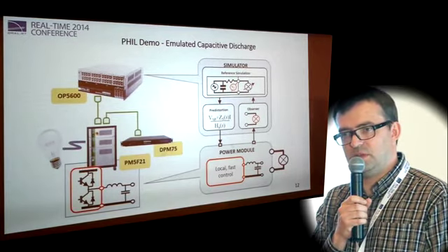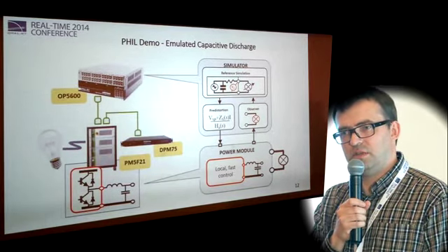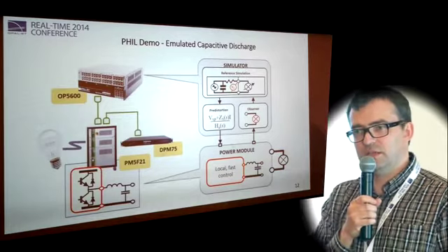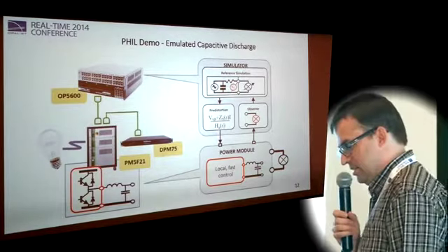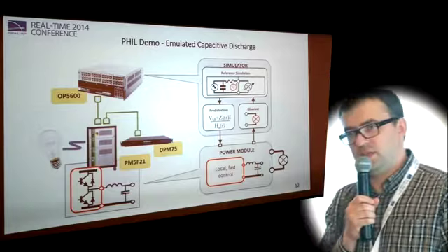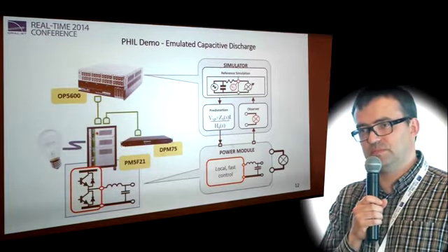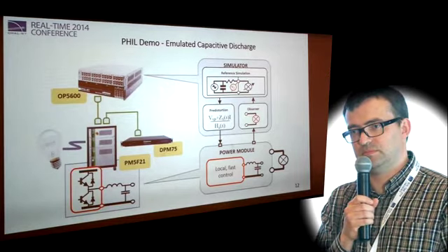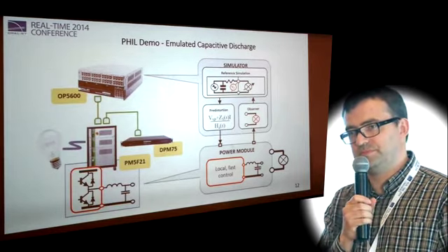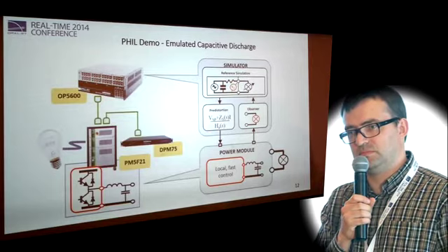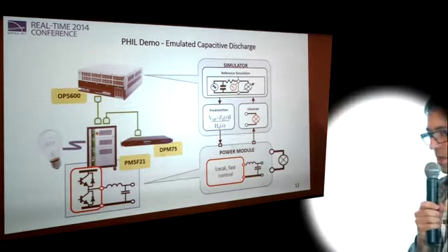For a delay, I can understand it can be compensated, but what about the slew rate, the dynamic response? If we use this amplifier as a motor emulator, for example, and there's a fault or a fast dynamic, a torque change, would that be accurately amplified for the response?